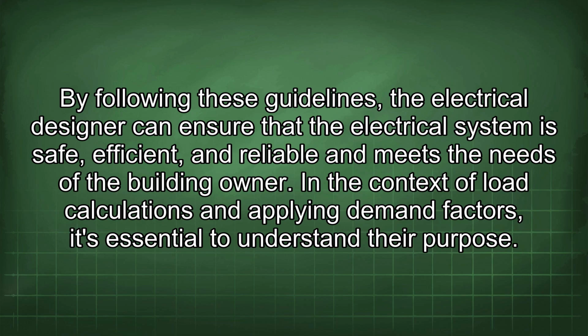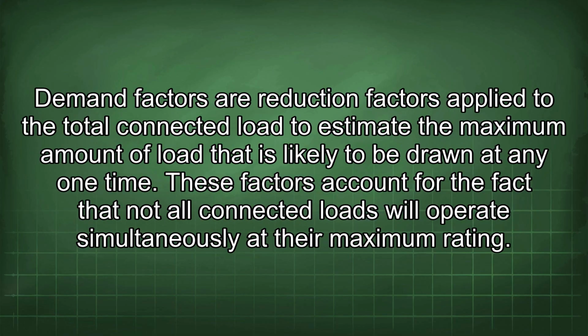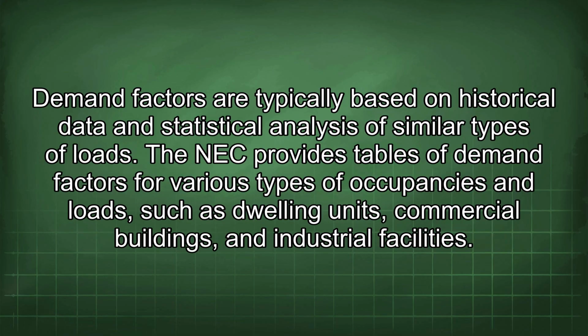In the context of load calculations and applying demand factors, it's essential to understand their purpose. Demand factors are reduction factors applied to the total connected load to estimate the maximum amount of load that is likely to be drawn at any one time. These factors account for the fact that not all connected loads will operate simultaneously at their maximum rating. Demand factors are typically based on historical data and statistical analysis of similar types of loads.